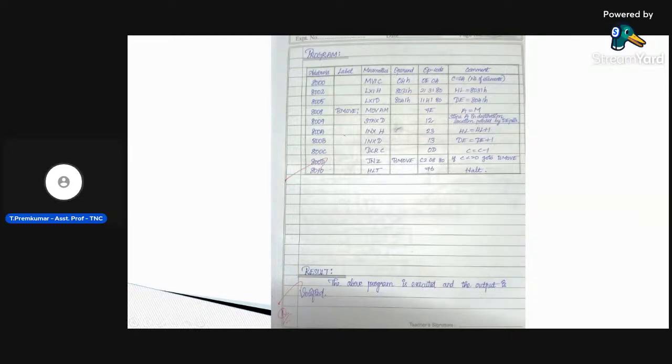So first, one data has been moved from the memory location HL to DE. Next, we have to take the second memory location data from the source, and that has to be copied to the destination. So that is what we're going to do. And before doing that process, we decrement the C register. It was initialized as 4, now it has become 3.